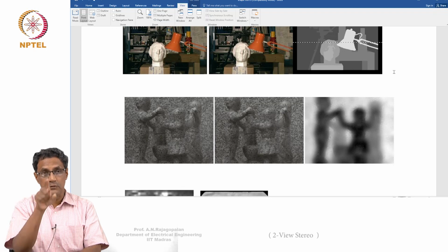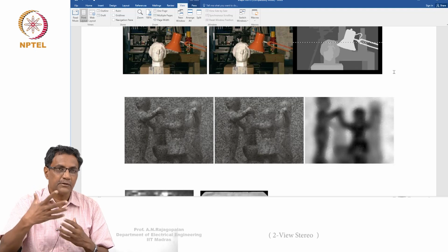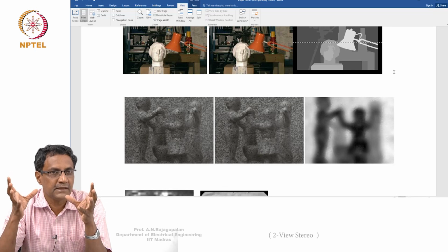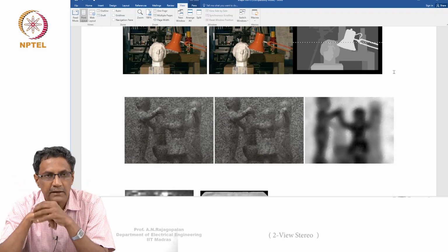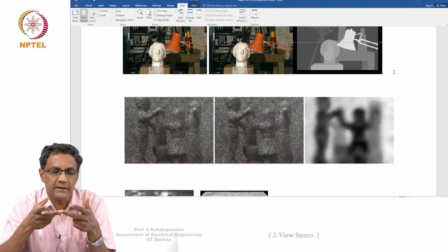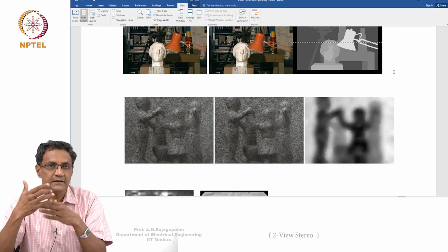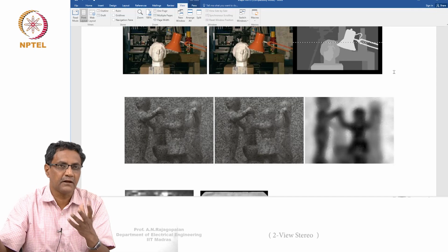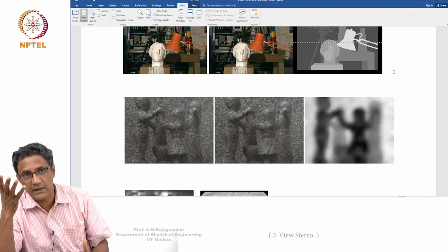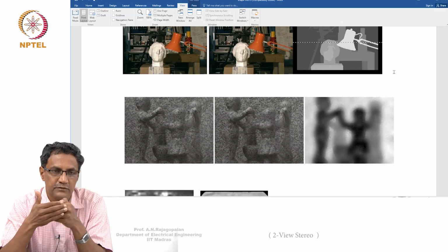But this Panasonic thing, that is not what all other phones do. They capture something like 30-40 frames and then quickly run a measure, because relatively you know where things are coming into focus, and then you freeze those lens settings. But this one apparently runs at 100x speed, because it just uses two images, computes a rough idea about where the object is, and then captures a bunch of frames around that. It doesn't capture 50; it probably captures just 10 frames around the place where it senses the object is, and then does something very fast on those few frames.